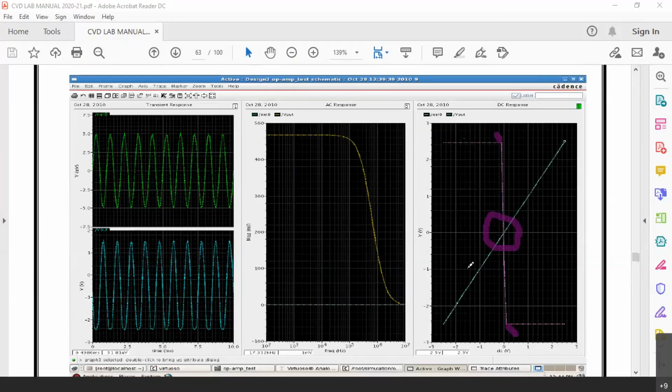We can use this like an amplifier in the open loop gain exactly here, because there is a steep change later on, because it is working like a comparator. But otherwise, when we connect a negative feedback, it is anyhow not going to saturate to the plus Vsat and minus Vsat, and we can use it as a regular inverting amplifier only when we connect a feedback.